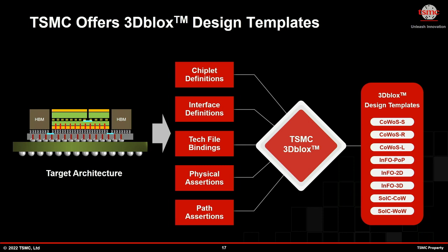They have all kinds of mapping files, from APR maps to DRC, GDS, from GDS map to RC tech file, or thermal tech file, or InFO tech file. There are more than 50 of them. And currently, without using 3Dblox, they are delivered as a bundle, and our customers would have to make sure they are using the right thing for their right purpose.